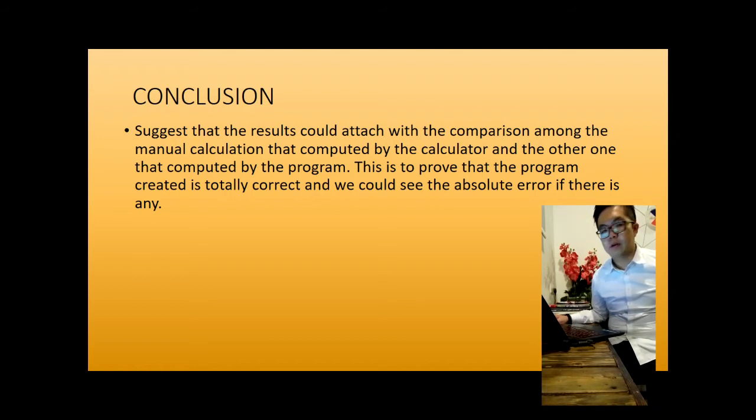From the project study, my understanding of this topic in practical application is augmented, and I could highlight the relationship among the radius, water height level, area, and other variables with the resultant hydrostatic force. When the radius of the curved surface is larger, the water height level increases, the area also increases, and the hydrostatic force is larger. In short, when the surface is larger, the hydrostatic force on the retaining structure is larger.